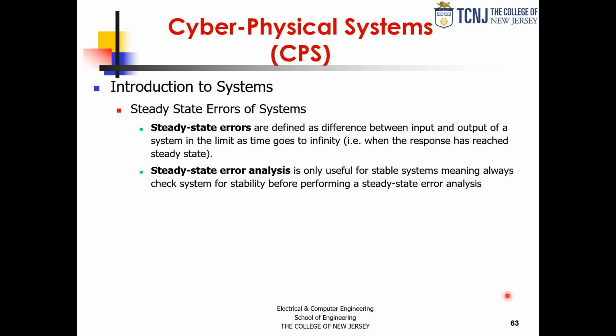Now, if it's bounded, but it's bouncing around a range, depending on what the system is meant to do, that system may not be stable, but it's not unstable either. It's what we call marginally stable. And some systems, we do want them to be marginally stable. It's useful that they are that way. So oscillators are such kind of system. But most systems, we want them to reach a steady state, because we're trying to control something.